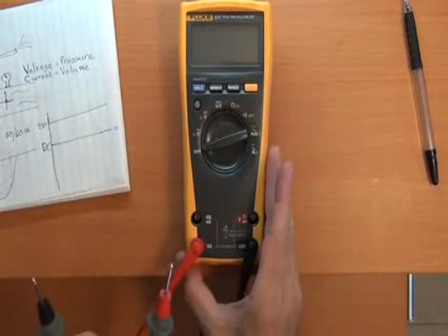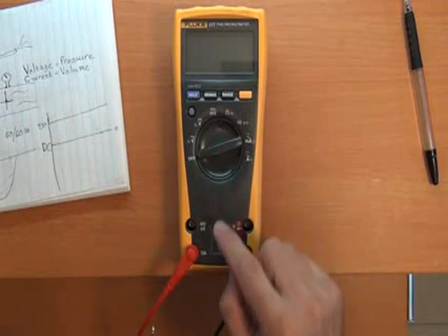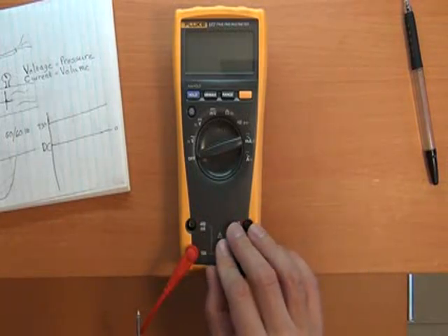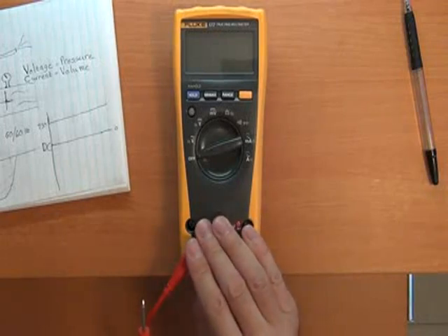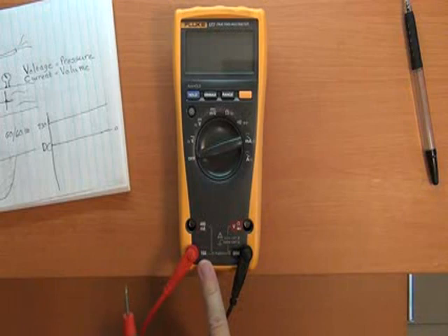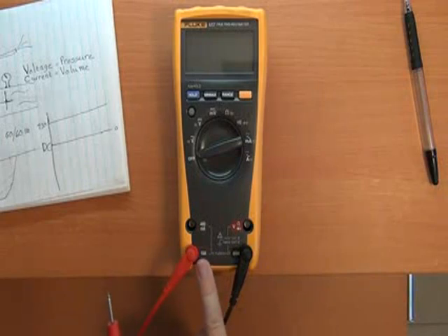And that's where measuring current can be a challenge, because your multimeter has to be able to handle that flow of current. And current can potentially generate heat, it can melt things if it's too high, and that's why by default most multimeters are only going to allow you to measure up to 10 amps. Some will allow you to measure 15 or even 20 amps, but only for a very short period of time. There's not many multimeters that allow you to measure higher than that.